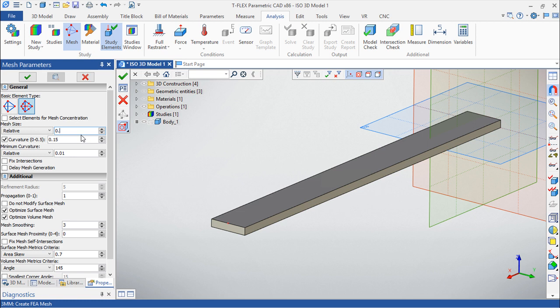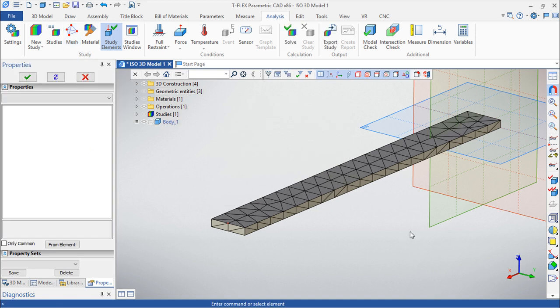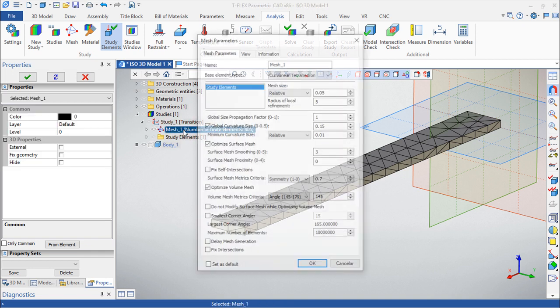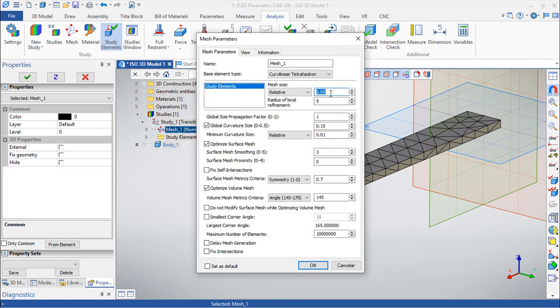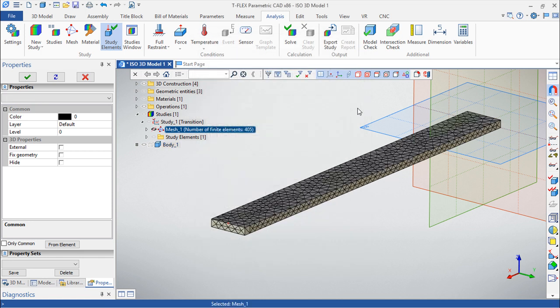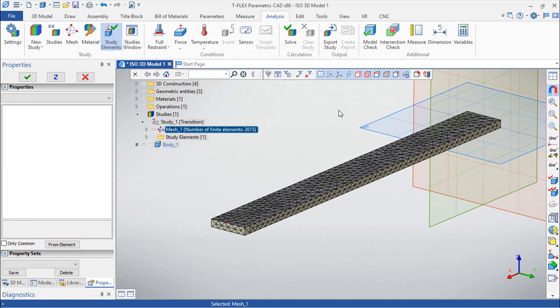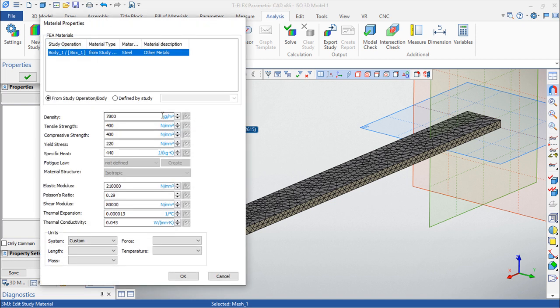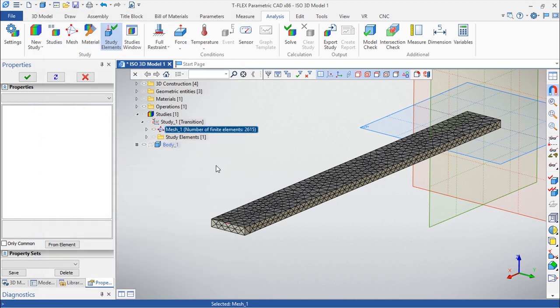I will create the mesh. We've spoken also about it. We can do it a little smaller. Instead of this, let us say 0.2, a little smaller, okay, better looking. So creation of the study, creation of the mesh, applying the material, you know, all of these concepts. The material I'm using is the one that was defined in the modeling. I can change it if I want, or change the characteristics of the material. For the moment I will leave it.